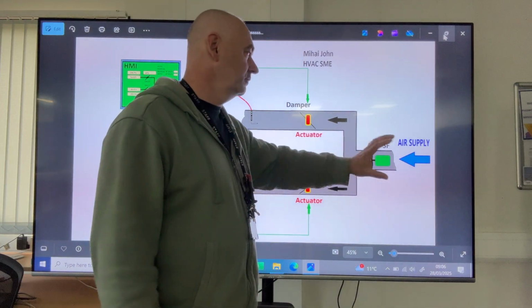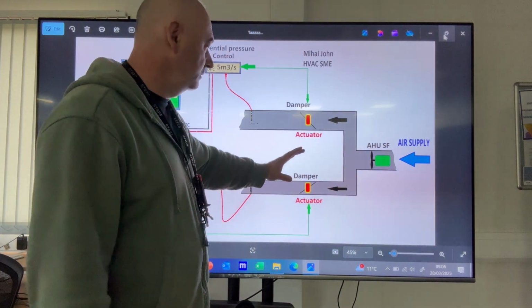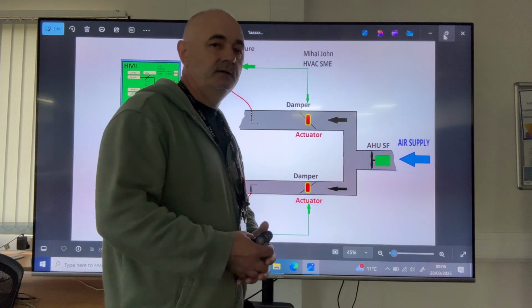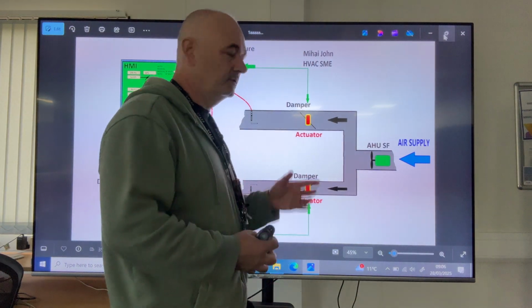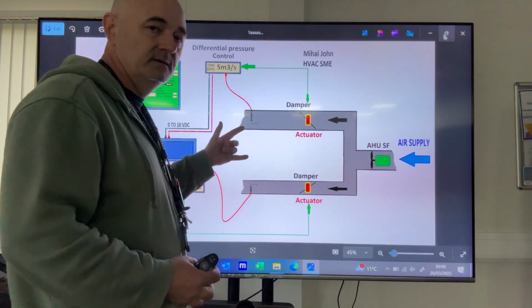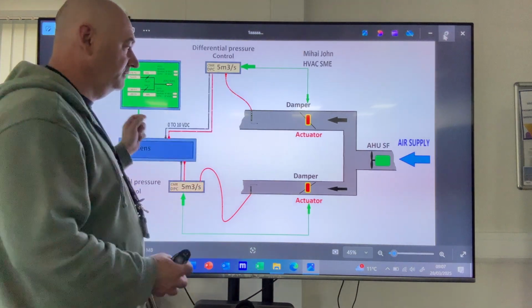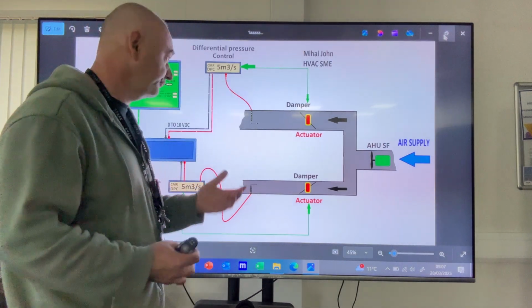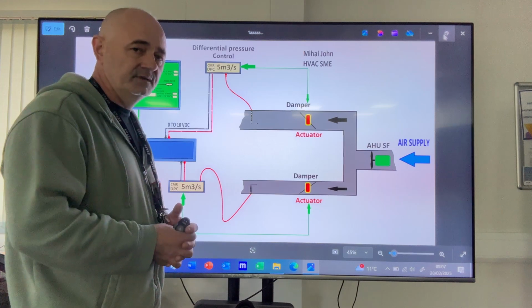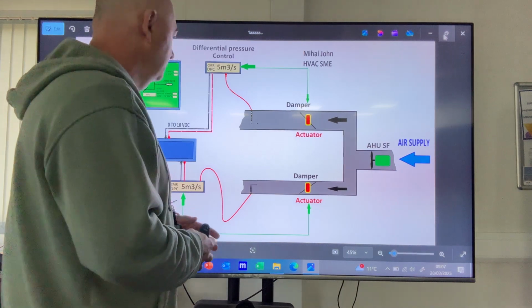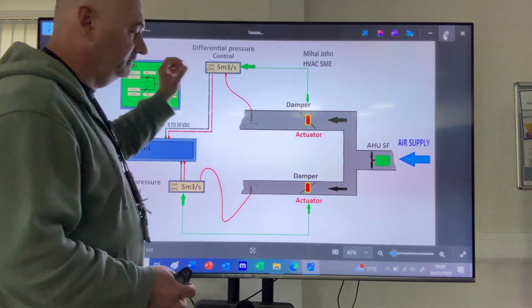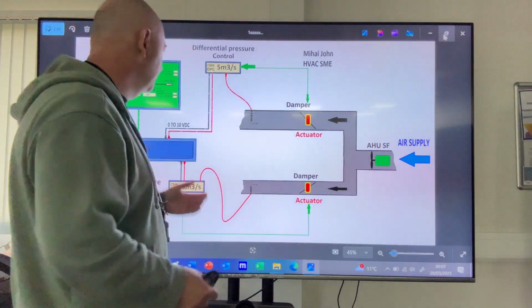So the engineers always force the AHU, but these dampers oppose the global airflow, because they were looking for their old set points. And when I discovered this, there are about 60 dampers which have to be checked and tested, and this system should be connected to the SCADA, so we have visibility.